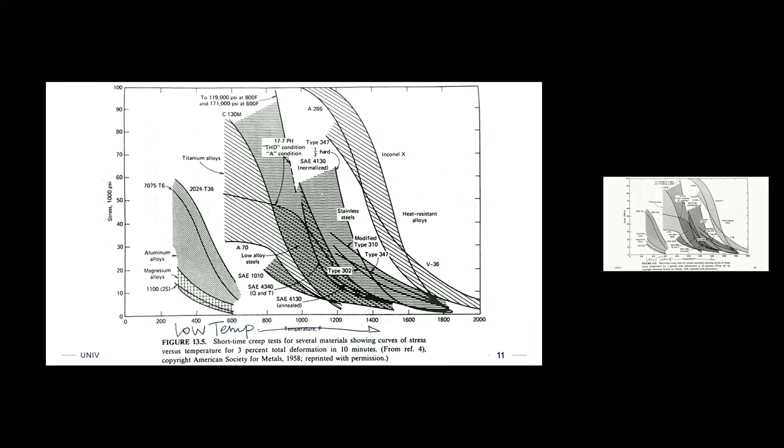So the left side of these regimes is how much, if it's at a constant temperature, how much the stress is dropping in 10 minutes. And then they stop it when they get to 3% total deformation. So you can see that the stress, if this y-axis goes from 0 up to 100 here, and it's in thousands of psi, so this is essentially KSI, then this material with these hatch marks, where I've kind of drawn this arrow, right, drops from an initial stress in the experiment, it looks like about 88 KSI, down to like, I don't know, 32 KSI in 10 minutes, right? So that's a significant drop. So these would be like stress relaxation experiments. So something is relaxing inside that material because of the constant load, elevated temperature, and some time in order to give that drop in the stress.